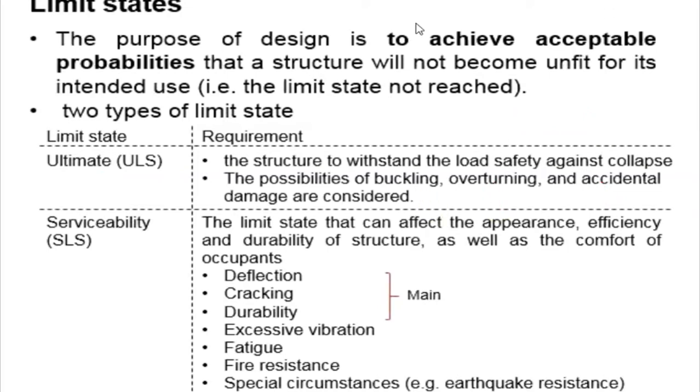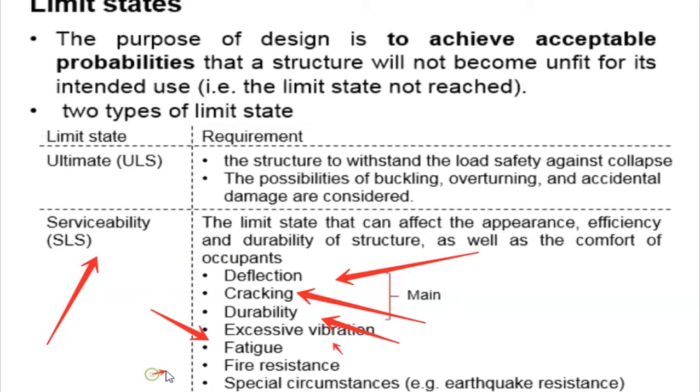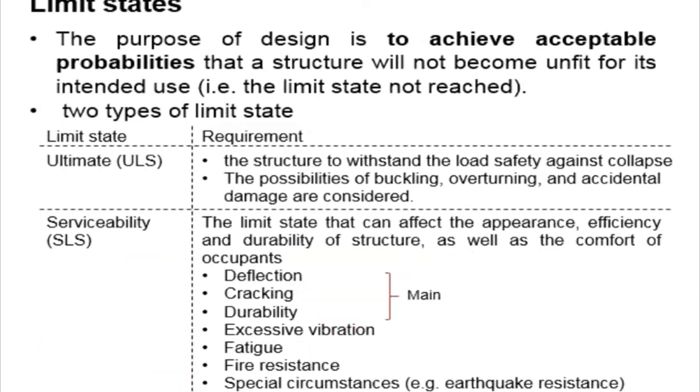But once you consider the design under serviceability, the requirement is that the deflection should be safe, as well as the cracking, the durability, the accessibility, vibration of the structure, the fatigue, the fire resistance. All these circumstances, even the earthquake, should be considered to be safe.